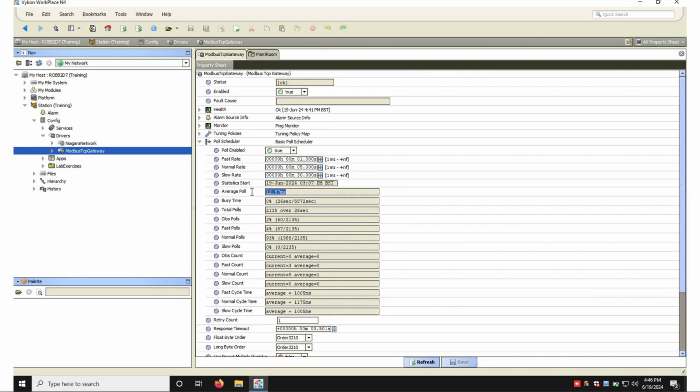So Modbus allows for 32 devices, but the master would be classed as a device, so potentially 31 slaves. But it's not recommended to really fill a network. You'd want to leave some capacity spare. And then you've got to consider the baud rate of that network. So is it 9600, 19200, 38400 bits per second?